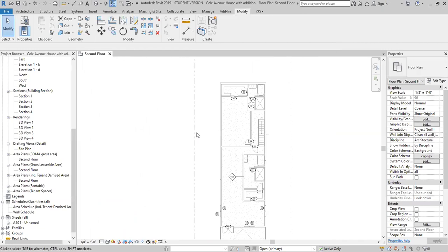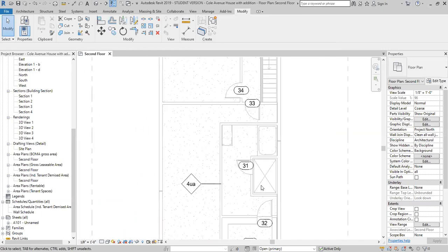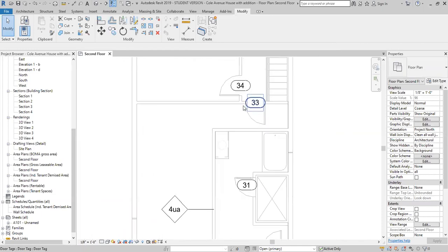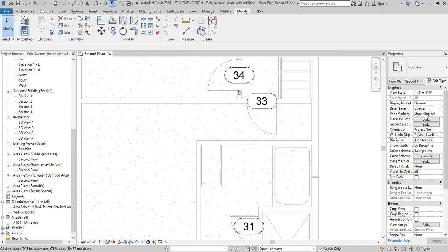The way you do it is you'll notice you cannot change these. These have to stay where they are and go from there. So I actually am exploring this option of taking this wall, extending it to here, and this being a separate piece. But there's a problem. It's in my main model right now. So what I'll need to do is click and go to my main model.